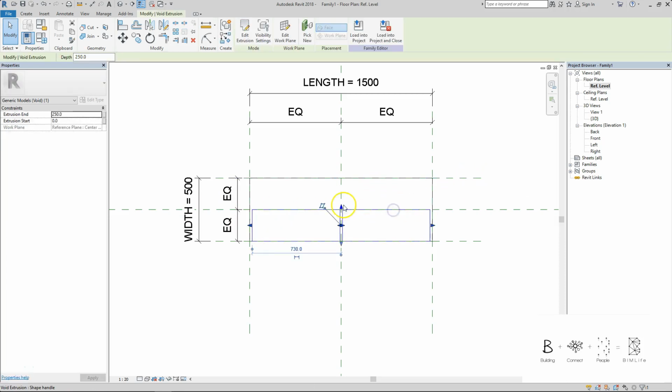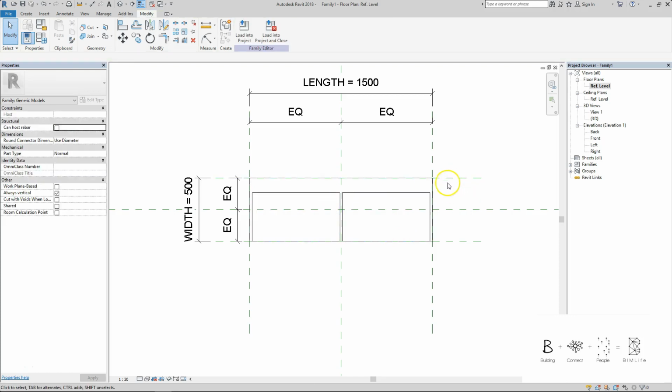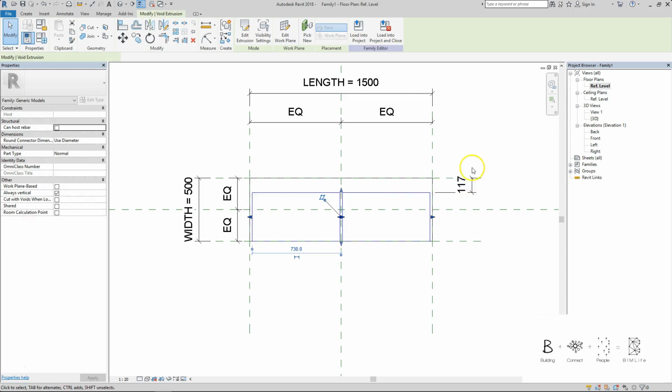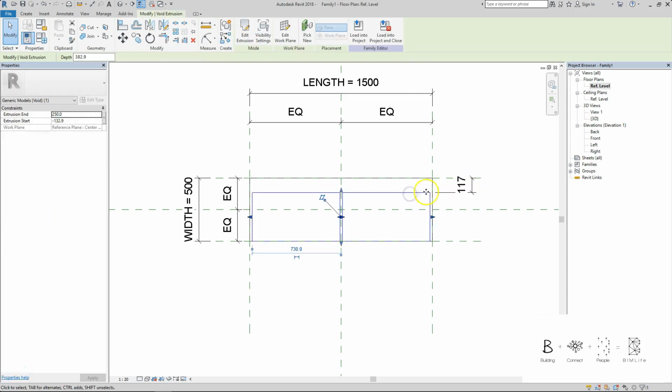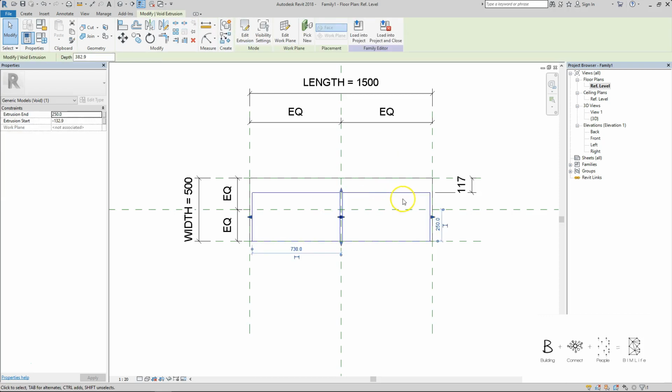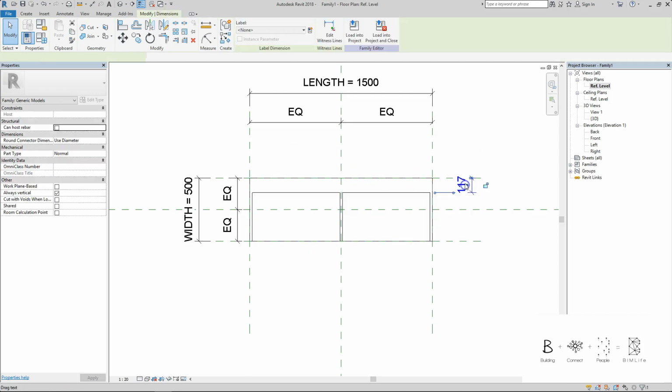So I'm just going to make sure that I can dimension 30. Once you do a dimension, when you click the shape, you will expect to be able to click on the dimension to change it, but you will find that it's not possible. So in order for that to happen, you need to click on the deassociate work plane, and you need to click on the shape the second time. Okay, this time it's not working, so I guess you're going to try a different method.